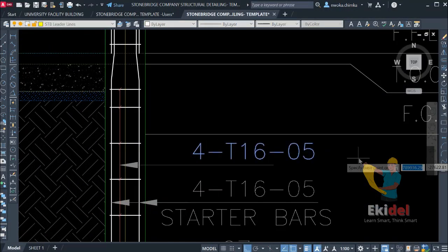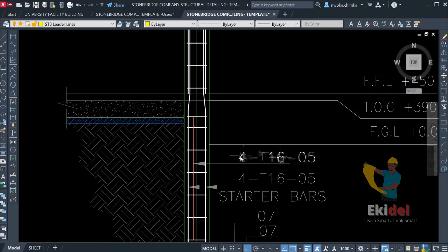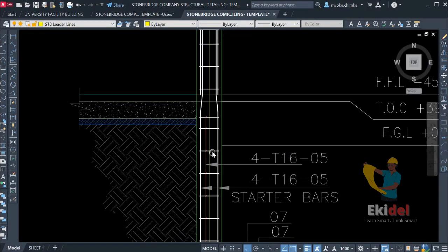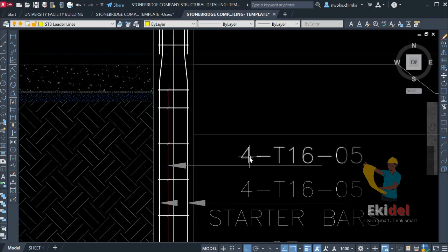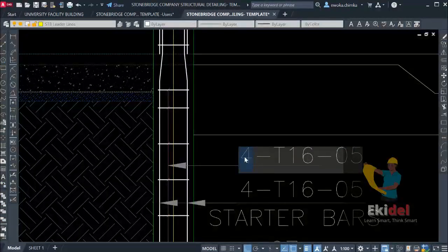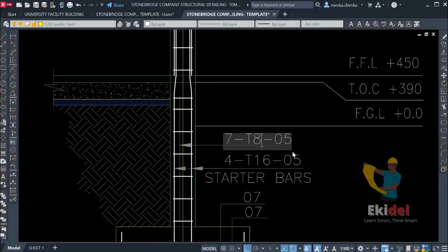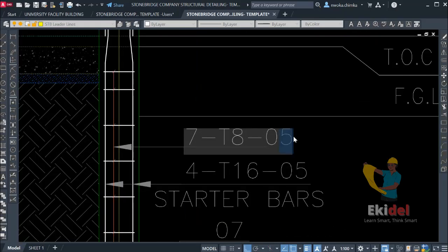So go and bring them downward again, and then show we have a number: we have 1, 2, 3, 4, 5, 6, 7, so we have 7 numbers of those links for that beam at diameter 8. You can see that. Now the bar mark, which we already have here, we already have 7 and 5, so I'll put this as bar mark 6.